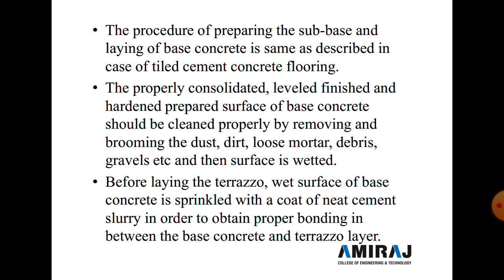Now before laying the terrazzo, the wet surface of the base concrete is sprinkled with a coat of neat cement slurry in order to obtain a proper bond between the base concrete and the terrazzo layer.